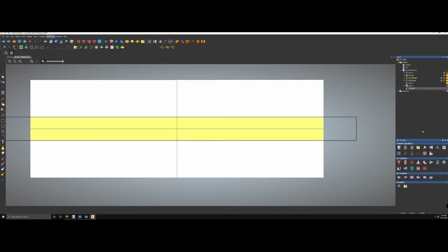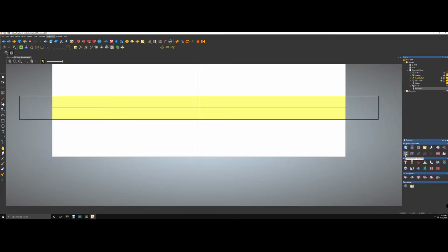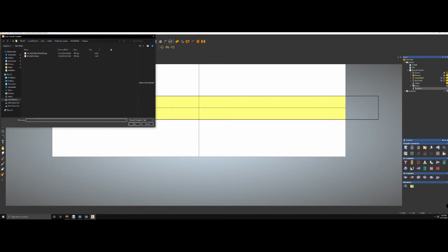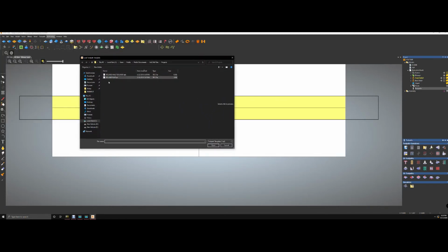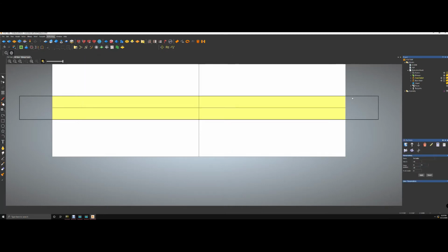When this is selected right there, you can move this here, you could adjust it. You could use the open button. Right here, I use the rolling machine. If you notice, I already have it assigned as rolling ring toolpath and rolling flat. So I'm going to select the rolling ring, and it's going to drop it right here for me. So you want to make sure this is open.